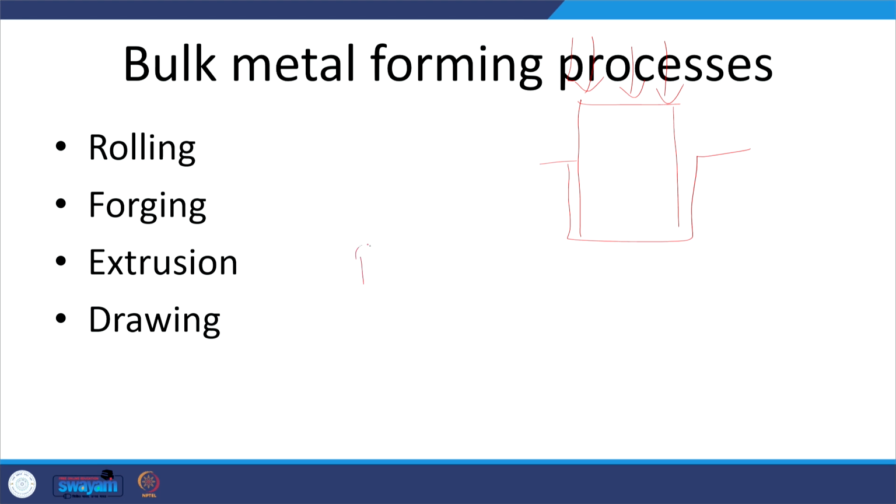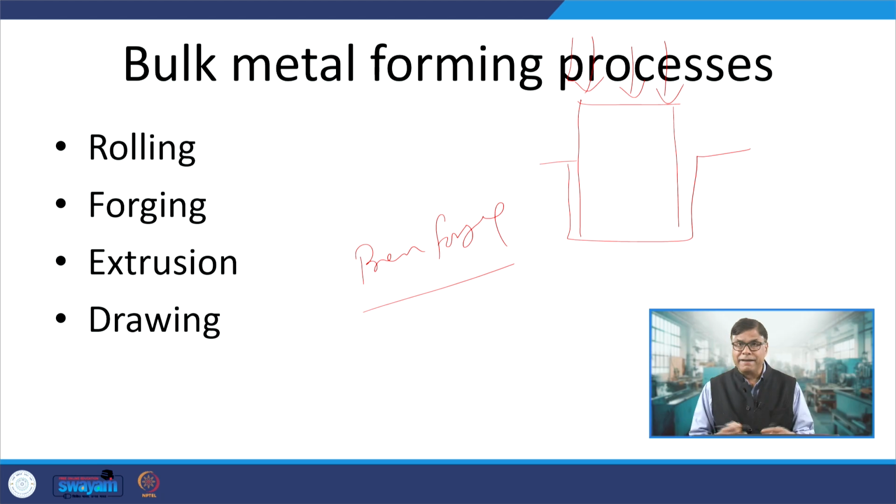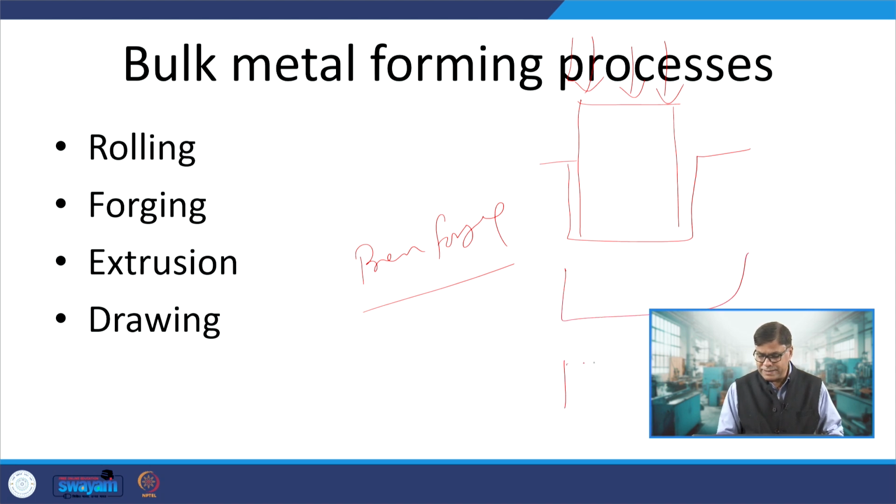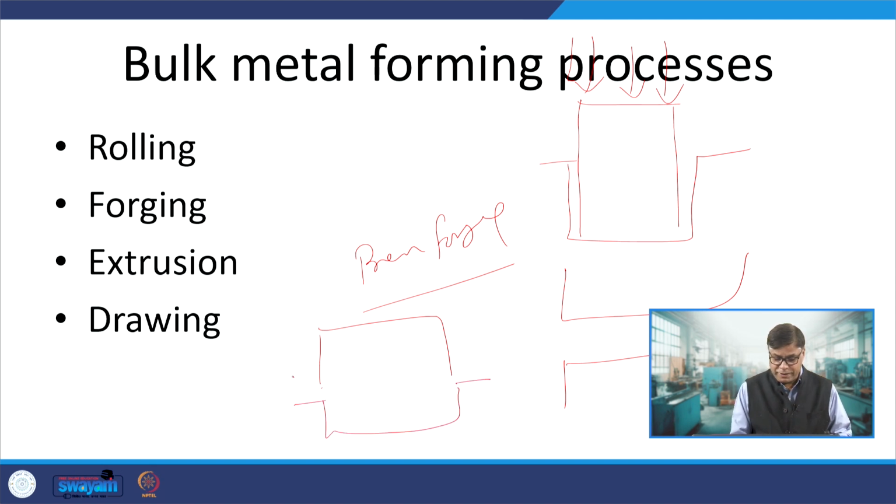But when the press forging is used, in that case the load is increased gradually until whole of the metal fills the die cavity. As far as open and closed forging is concerned, in case of the open forging, both the dies are open and the metal flows literally, while in case of the closed forging, we will have one upper die and lower die. So, in between we will be putting the raw material to be deformed.